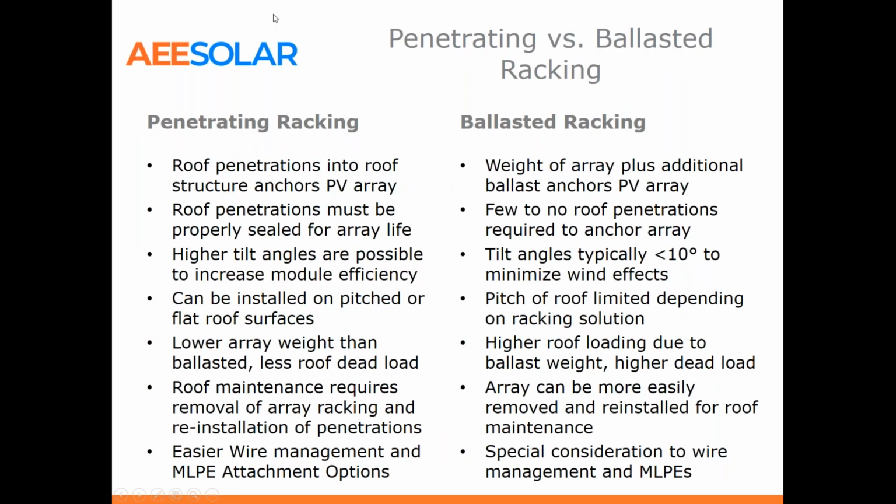So, some comparisons back and forth between penetrating racking and ballasted racking. Penetrating racking has roof penetrations into the roof structure. You anchor the array, and you have to seal those for the entire array life. We can get higher tilt angles. Ballasted racking is typically limited to 15 degrees or less. If you do have a project in the north of the country, or, for example, an off-grid system where you want to make sure you're winter tilting, we definitely want to go with a penetrating racking system.